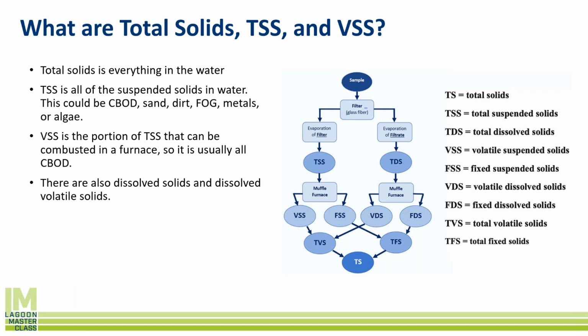Now, that particle could be dirt, sand, grit, hair, fiber, bacteria, anything that comes in your influent. On the effluent side, that total suspended solids could be floating sludge, inorganic particles, the bacteria that was doing the treatment, or it could be algae or even duckweed. And you can imagine if you just get one little piece of duckweed on that filter, that weighs a lot compared to everything else that's in your water, so that can actually throw your results off quite a bit.